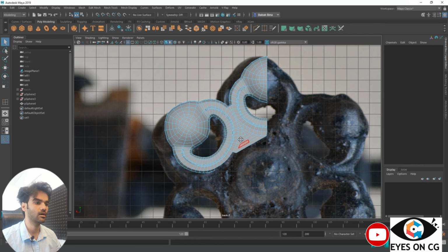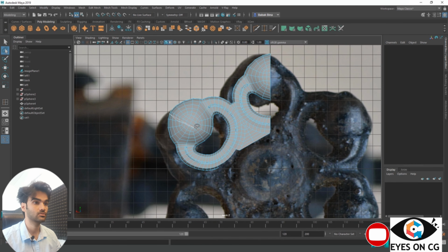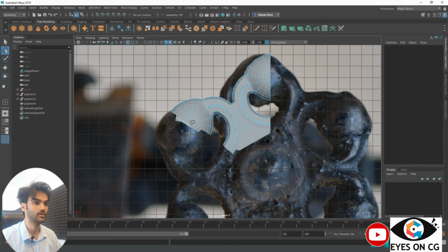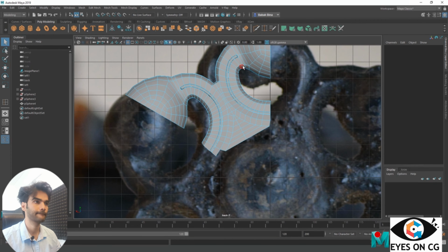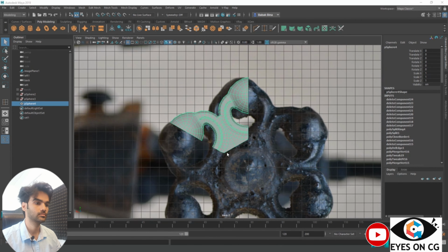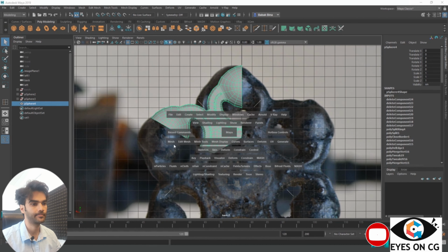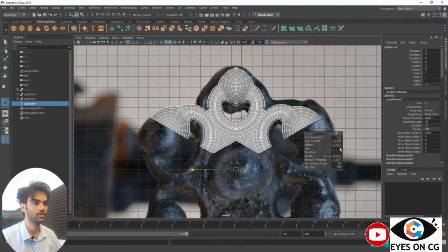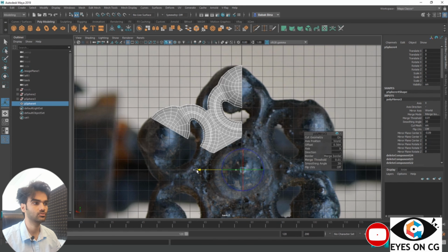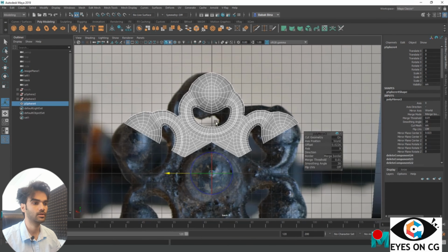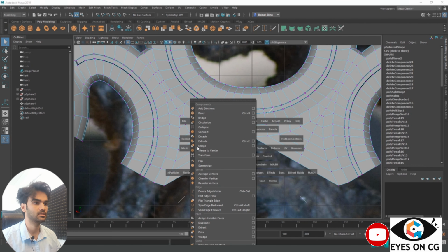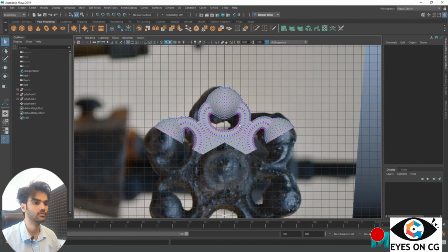So I get rid of that half, and I also get this also. Just select, I'm using this curve selection. So over here, I'm selecting those faces and delete it. Giving another mirror option and merge threshold to 0.01, and I'm going to mirror in the x-axis. Now you can see it merged these vertices and we have deleted the unwanted vertex.